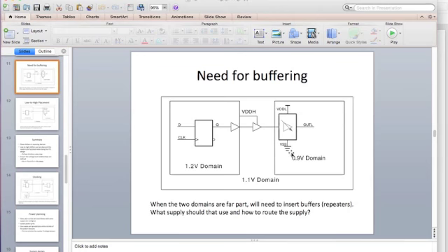Okay, so this is a good comment from Arnab: where can we put the level shifter from a power perspective? Why not put the level shifter in this example from the receive side to the transmit side? The advantage of that is that the wiring capacitance and the power required to drive the interconnect will be lower, because I am going to be using a lower voltage supply to drive that. And that is true, yes.